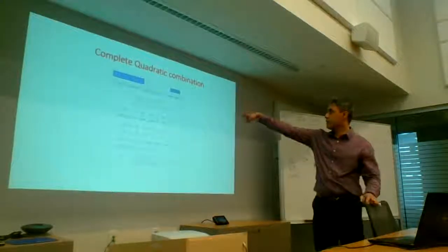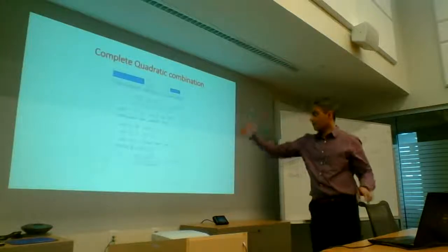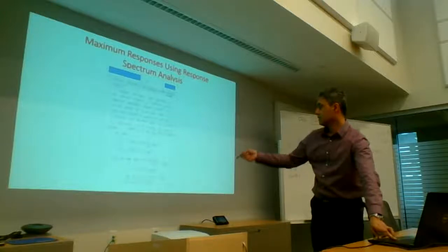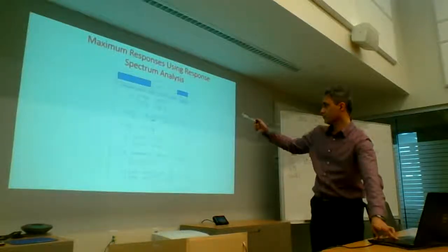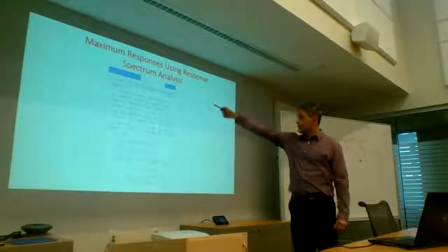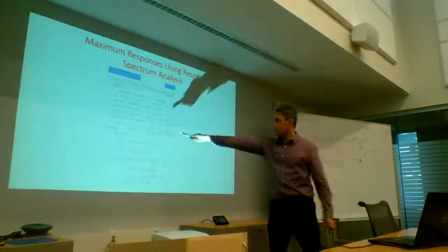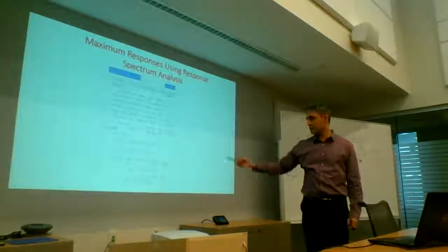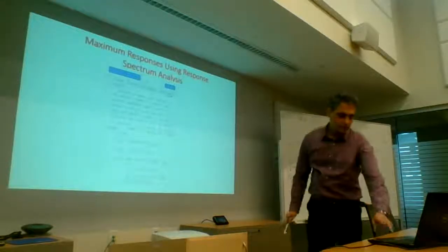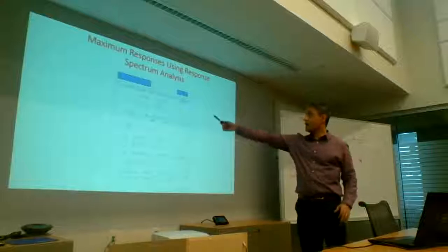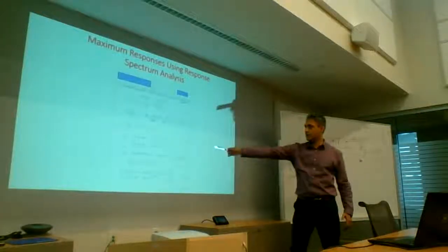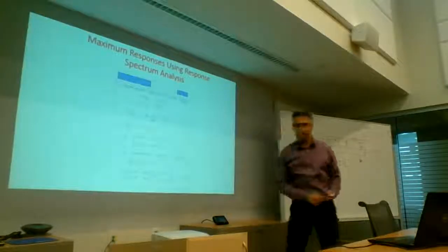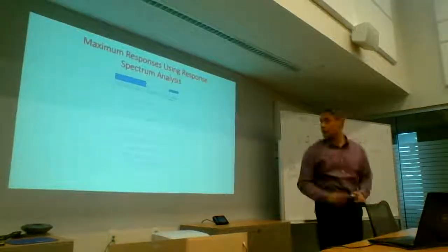But this is the form of it, and I'm not going to go through this, but in these notes, you'll see an example that kind of shows you how to go through this whole thing. So it's the same bent, an IE of 0.45 Ig, EC value, and a spectral acceleration. There's your mass matrix, the K, the stiffness matrix, so that becomes that. Then there's your characteristic equation, right? All the things we've talked about.